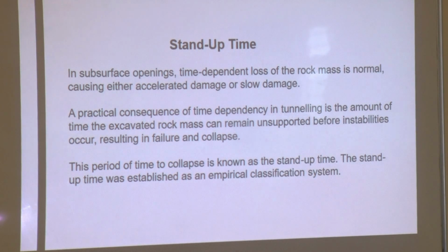So within that time, the rock is unsupported. So how much will the rock layer deform? The time for which the rock will retain itself is basically the startup time. So the startup time is very important in tunnel excavations.